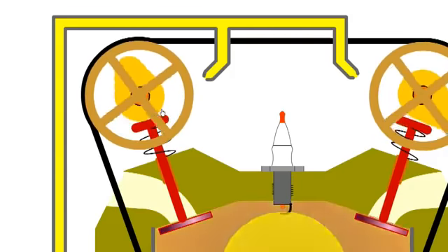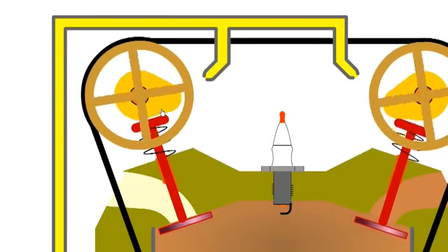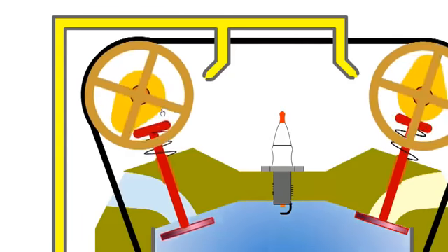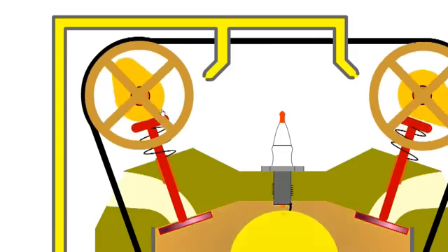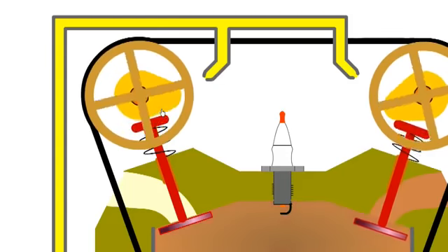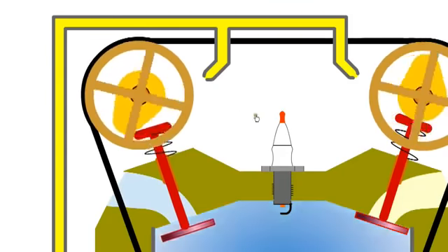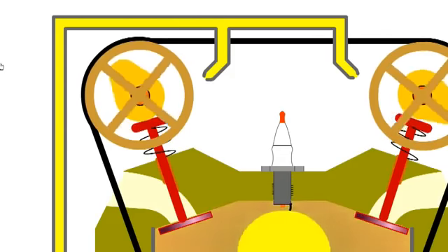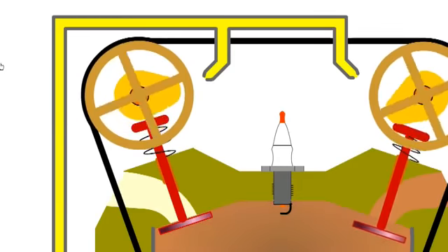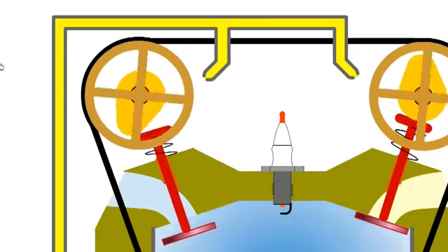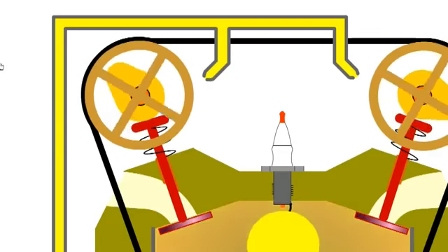In the past, the ventilation was vented to atmosphere, but this was considered a source of hydrocarbon emissions. The PCV, positive crankcase ventilation system, routes combustible gases to the intake manifold where they are burned, thus reducing emissions and preventing overpressurizing of the engine.